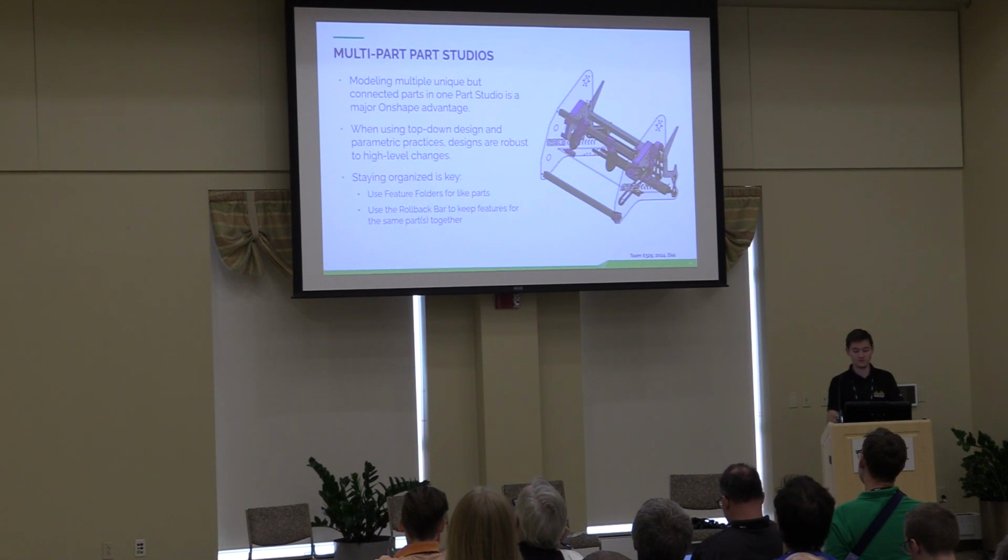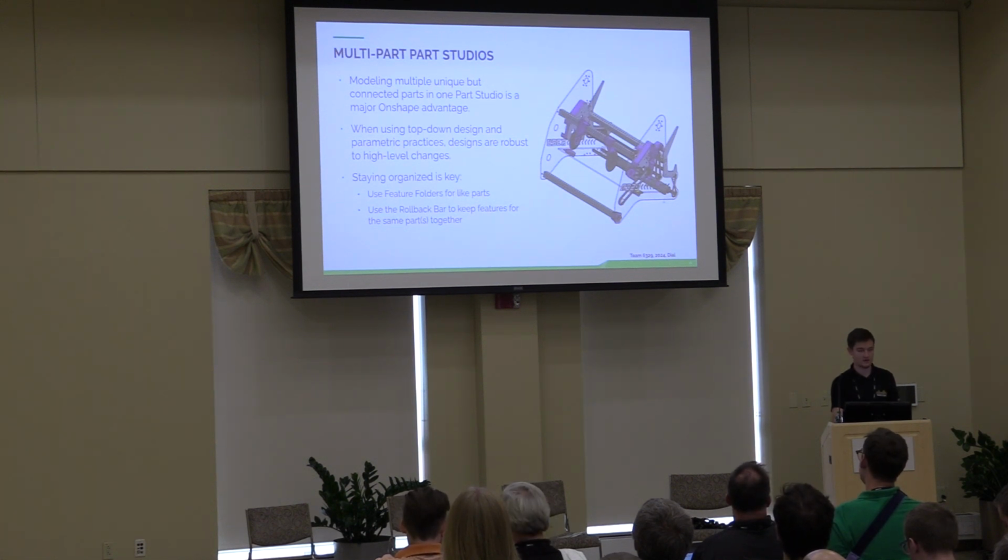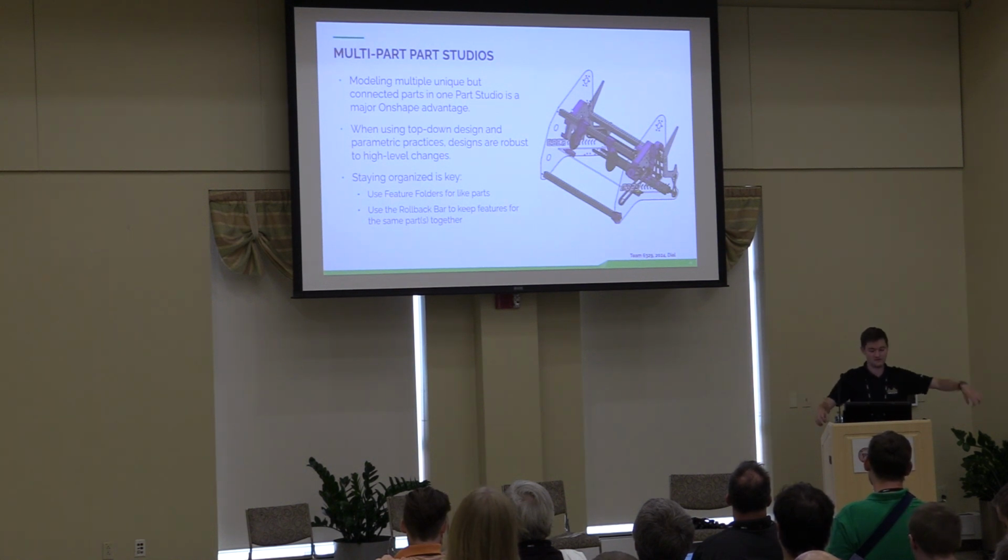This is just how it was built up, and this was great because we knew where this plate was, so in reference to that plate we could just run pieces one by one across and do an up to face. So if the shooter changed dimensions, wider or narrower, everything else that depended on that just automatically updated in length. The shafts updated in length. Everything was driven by that top level geometry. So it was super simple to know that it was going to fit the first time. You were not making a file and saving it, making another file and saving it.